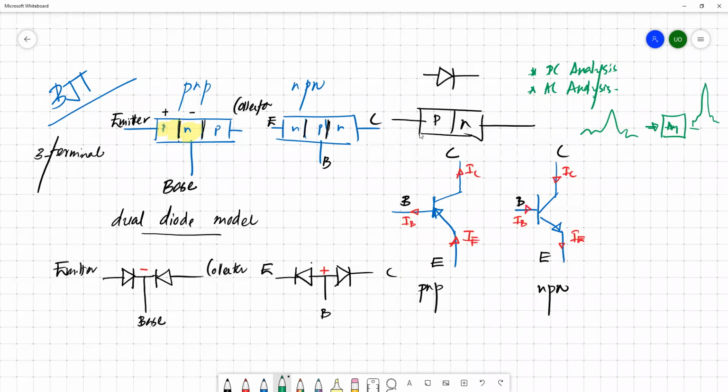At the same time, to operate this transistor the way we want, we need to make this transistor work at a particular level. So we have to set certain parameters to operate this transistor as we want. This is called biasing of the circuit. To do this biasing for the transistor, we need to do some analysis which is concentrated on DC components only, DC currents and DC voltages. Based on these DC voltages and currents, we can find out the resistors which we need to place on these terminals and the rest of the circuit. This is basically called DC analysis.